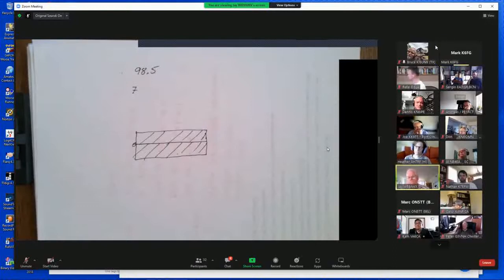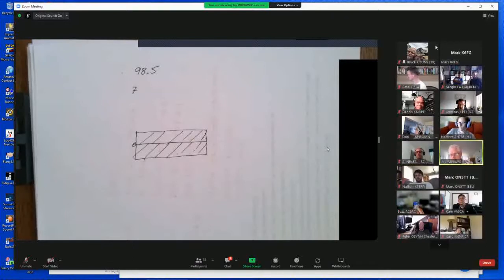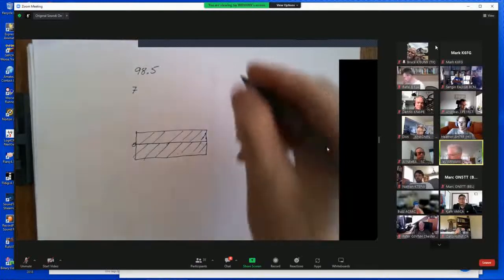Okay, might it be intermod? I was thinking of that, but she says that there's a subharmonic relationship. If it would be intermod, first of all, you'd probably hear 2 stations, unless the other one is a dead carrier. And she's getting a relationship between her internal oscillators. Excuse me. This is, by the way, the Elecraft, you said?